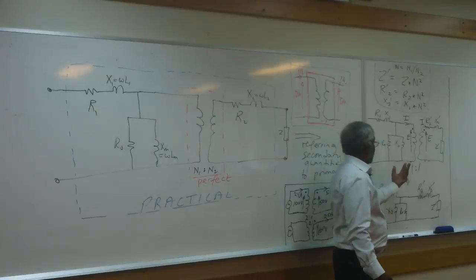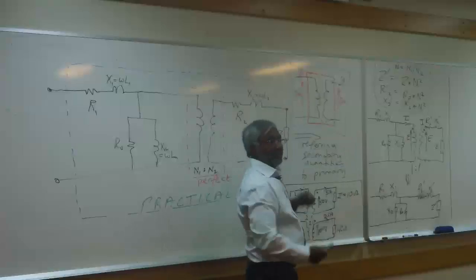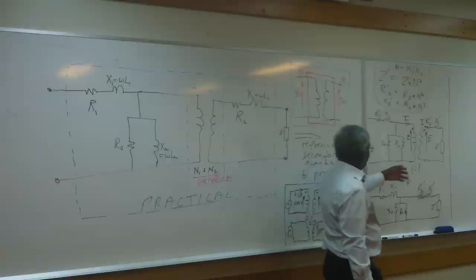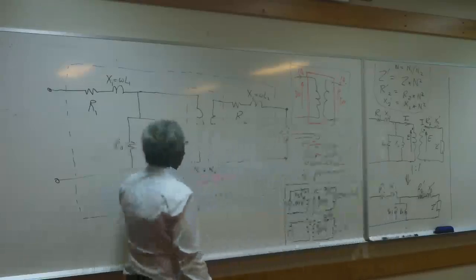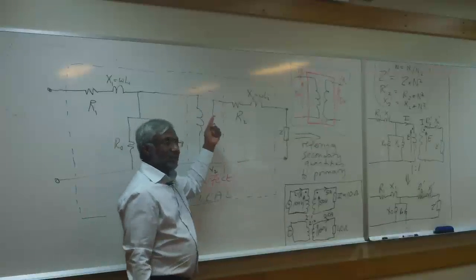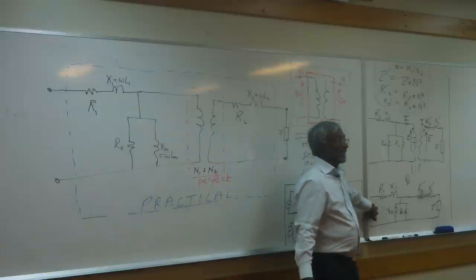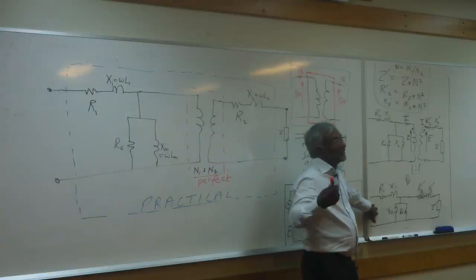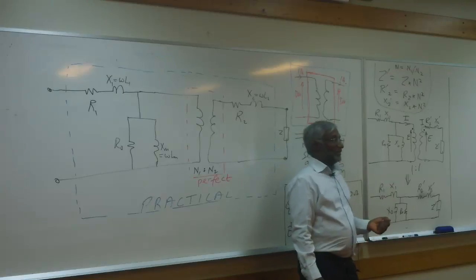In doing that, you're able to replace the perfect transformer by a pair of wires, which you have done, and therefore now you no longer have 2 electrical circuits coupled by a magnetic circuit. You now have, what do you have? What's this one? How many electric circuits there? 1. Just 1. So 1 electric circuit, no magnetic circuit to worry about.